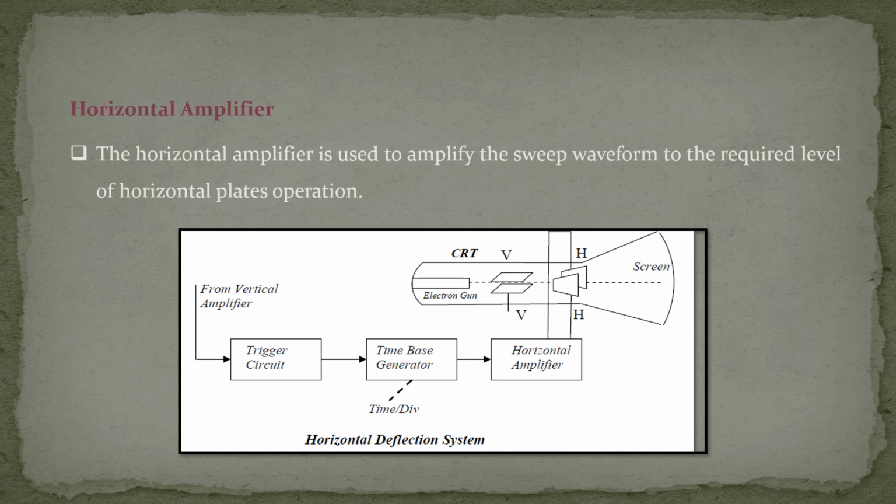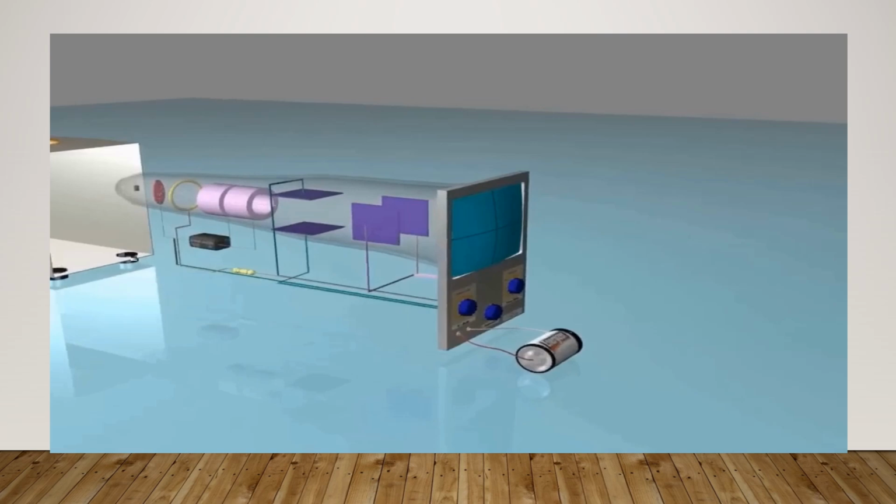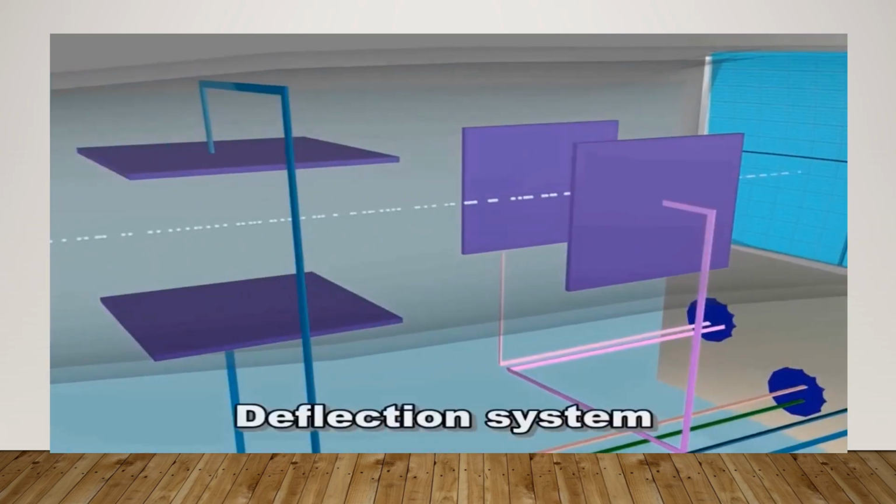Horizontal amplifier. The horizontal amplifier is used to amplify the sweep waveform to the required level for the operation of the horizontal plates. The second part of the CRO is the deflection system, a system that is responsible for the deflection of the beam of electrons from its original straight line path.